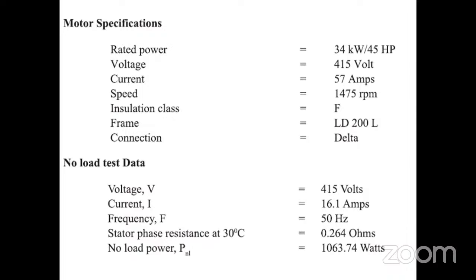Speed is 1475 RPM. Sir, in this case, what is NS, synchronous speed? Can you say, please? 1500. Yes, sir.